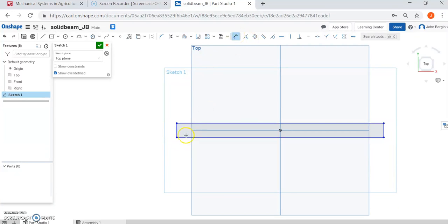When I come over here and make these dimensions, I'll draw over. You can see right here at 7 inches, you can see that these lines right here turned from blue to black. And when that did that, that means that those lines cannot change their relationship between each other. They're locked in at 7 inches.